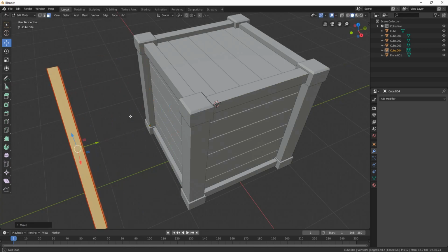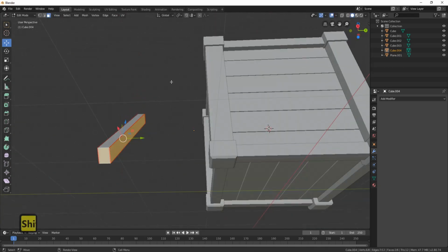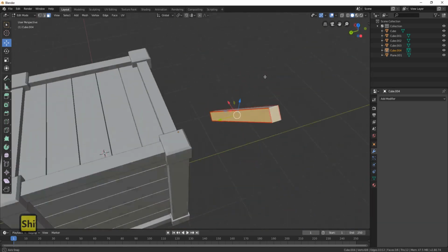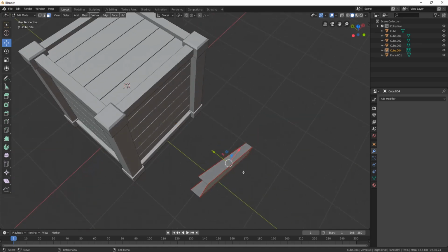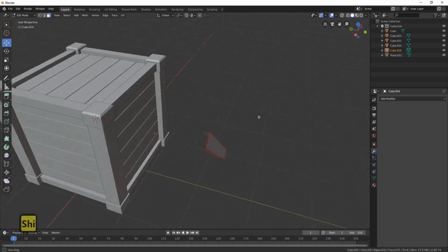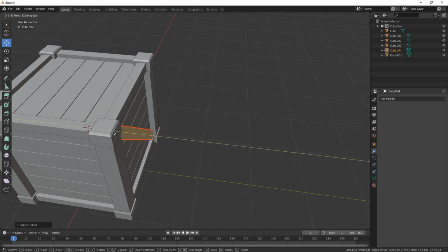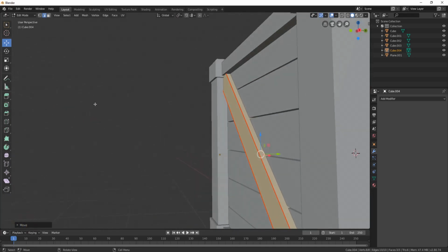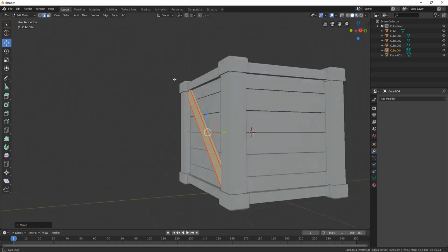I'm going to drag it back out, and again I'm going to tidy it back up, because we're going to mirror this as well, and we don't want these seams here, these faces here, sorry. So delete faces, and you're going to end up with something like that. Now we've got rid of those, let's grab it. So L, on vert select, so press L when you're hovering over it, and let's drag it into place. Basically you want to put it in the place where you're going to be happy with it. So just under here looks pretty nice to me.